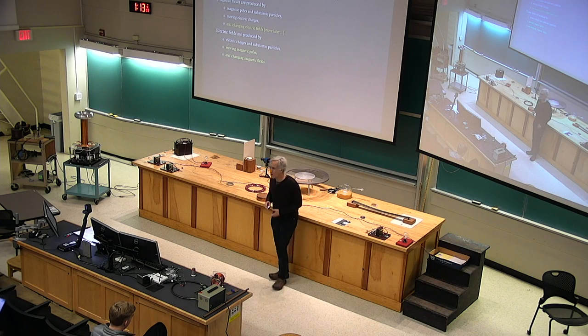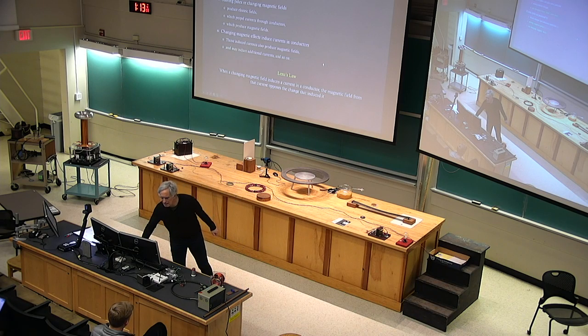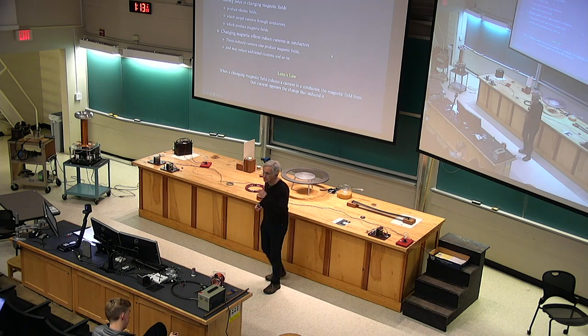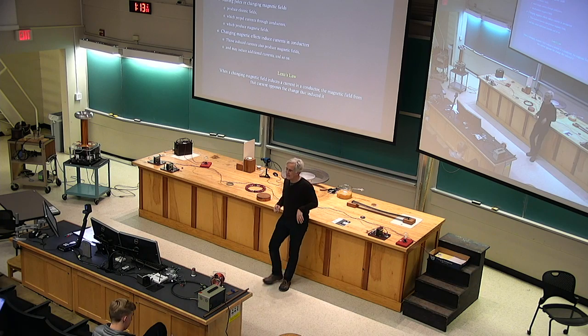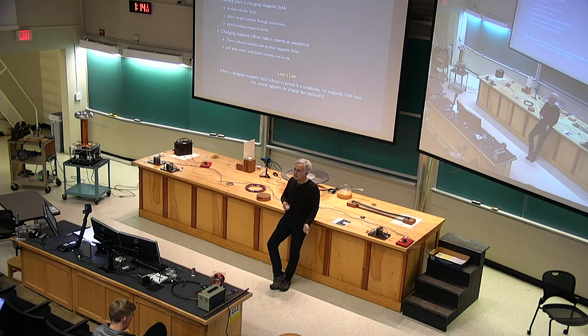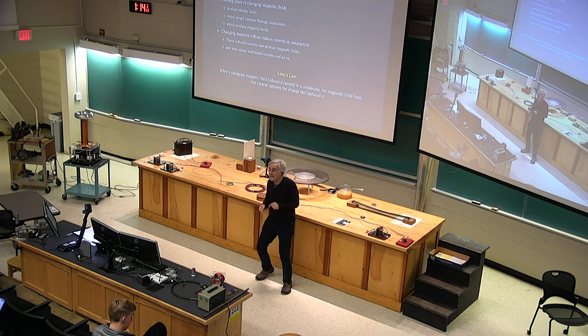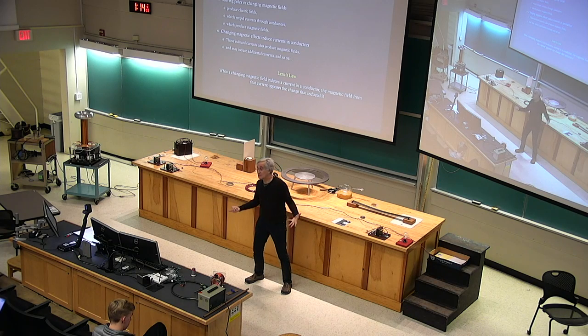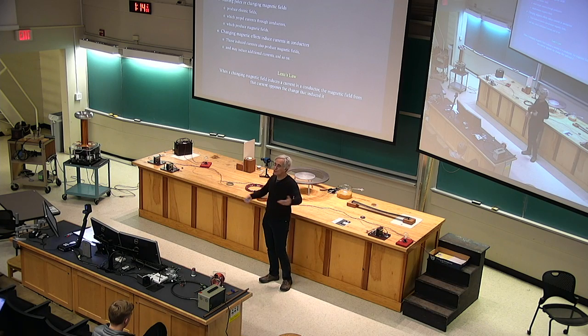This is actually known as Lenz's law, which I haven't put up there before. There it is, Lenz's law. You can get it in its wording, but I want you to get a feel for the reason for it. When a changing magnetic field induces a current in a conductor, and that's what we've been doing, I've been inducing a current by playing with a magnetic field, either moving or changing. It induces a current. Underneath the word inducing is the longer story. That moving or changing magnetic field creates an electric field which causes current to flow. That's induction, okay? So it's inducing a current.